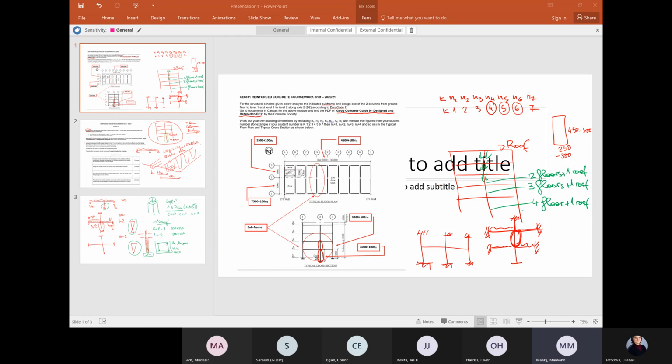Yeah, Diana, for the effective length, obviously we have K1 and K2. If both ends are fixed, then K1 is equal to K2? You're looking at the subframe for the bending moment in your column, right? Yeah, the effective length. The effective length you'll determine with the K factors, K1 and K2. So you see in the presentation we have the stiffness of the column divided by the stiffnesses of the beams at that end, so let's say for the top end of the column.